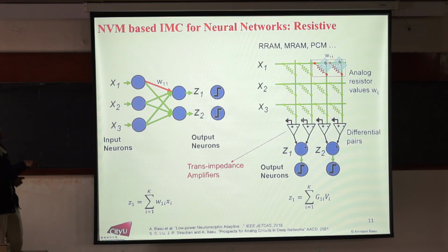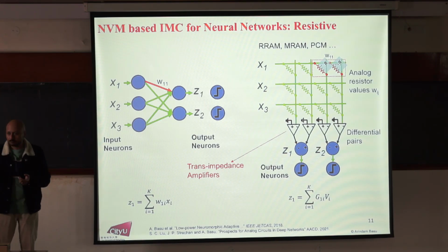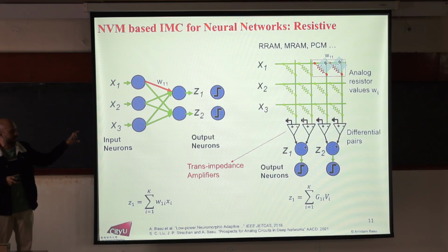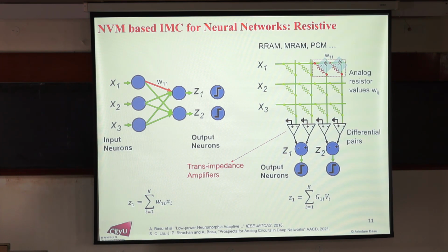Yeah, so here what I'm showing is this transimpedance amplifier outputs are getting subtracted out, right? Now, the subtraction you can do in n number of ways. If you are doing current mode, you can use a current mirror to mirror the current and subtract it out. A lot of people do separate ADCs on the 2 lines and then subtract in digital. So you can do a variety of approaches.